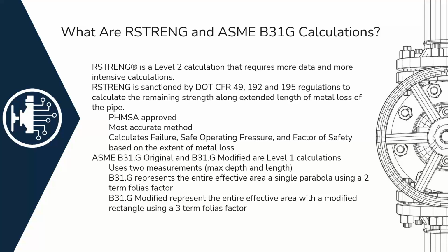Whereas RSTRENG, a level 2, does multiple increments, basically mimicking the morphology of the pitting itself, particularly the river bottom. In other words, this is what we're dealing with: the deepest point as you're going along the pipe axially, okay? Well, that came about in 1989, okay?